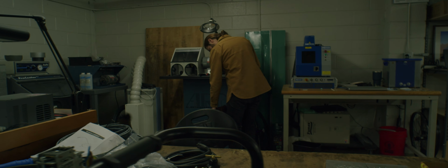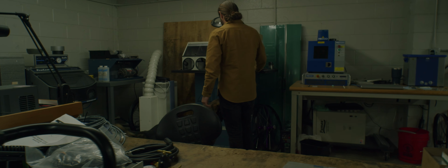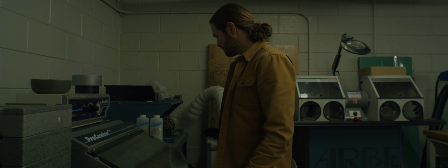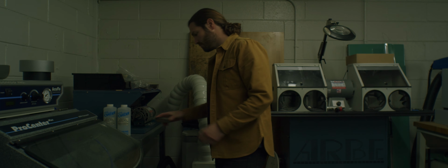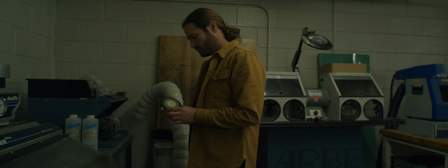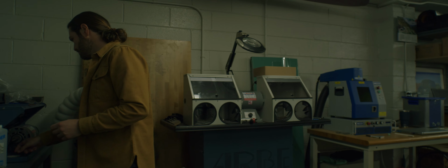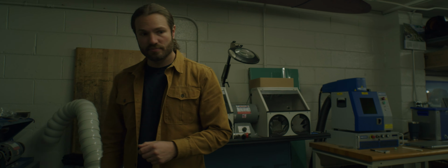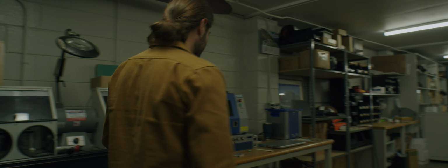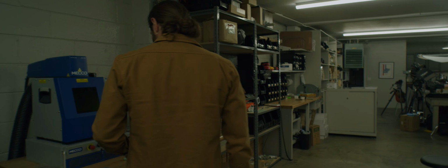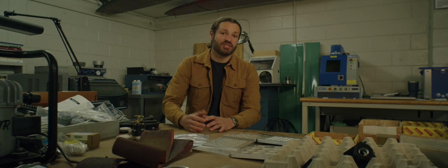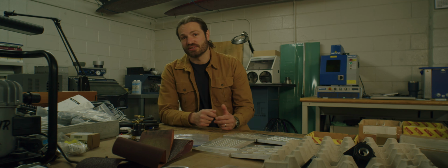As a watchmaker, we always go the extra step to add decoration. Things like Geneva stripes, polished surfaces, brushed surfaces, vertical, horizontal, circular brushing. All of these things are finishes, and those will be applied using a number of different machines. The machines sitting behind me are the ones I use for finishing.